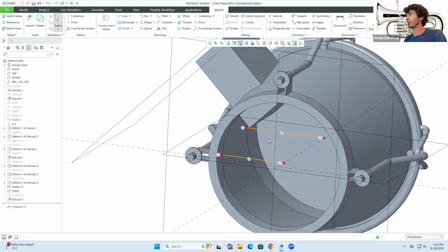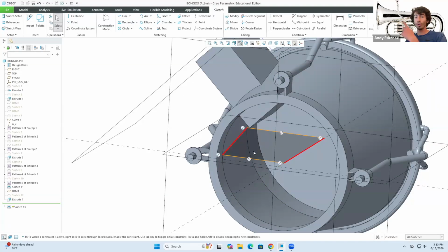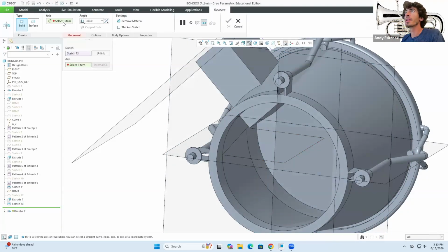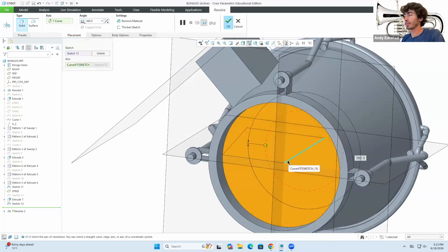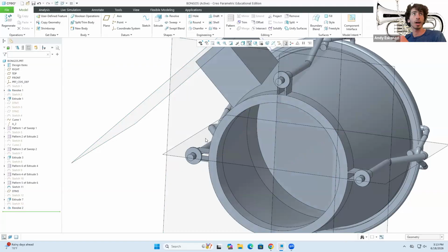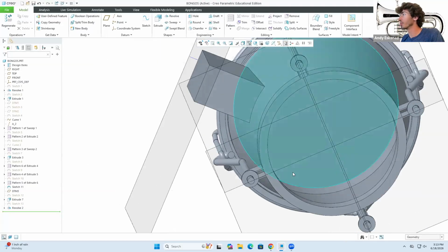So I'll come with a projection of that. Then I'll do a line that will come like this, another one that will come like that. So now what we can do is go here to OK, and then go to revolve. We're gonna select that axis, but really we don't want to do this fit, we're gonna do a remove. See how that appears in this frame.